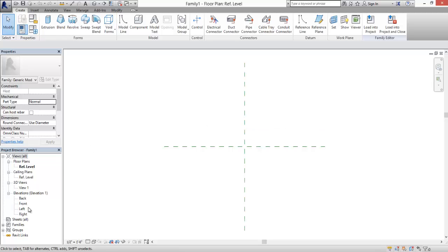And then over here we see essentially the same view layout. We have different tools though in the create tab. Instead of it being doors and walls, we have extrusions, blends, sweeps. So all of the modeling can be done with these five tools. It might not seem like you could do that, but you can. So you'll model all of the solids, and then you can subtract from those solids using the same set of tools, only in void format. Okay, so literally everything can be done through these tools.